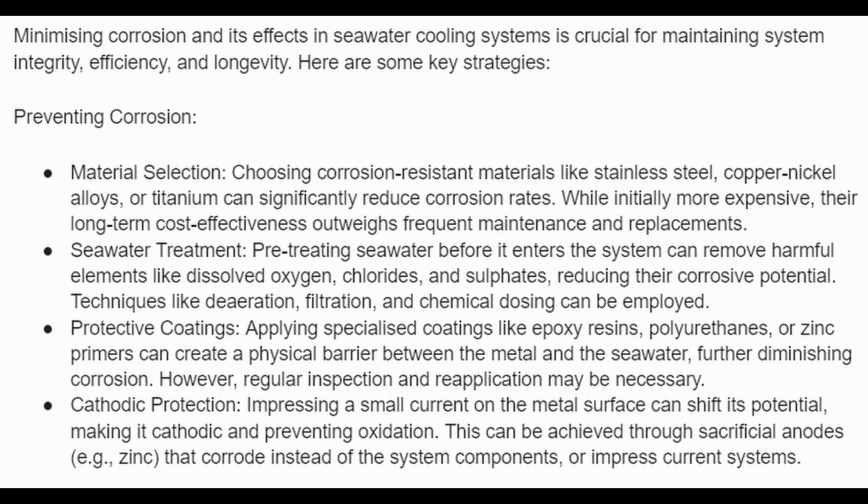Seawater treatment. Pre-treating seawater before it enters the system can remove harmful elements like dissolved oxygen, chlorides and sulfates, reducing their corrosive potential. Techniques like de-aeration, filtration and chemical dosing can be employed.